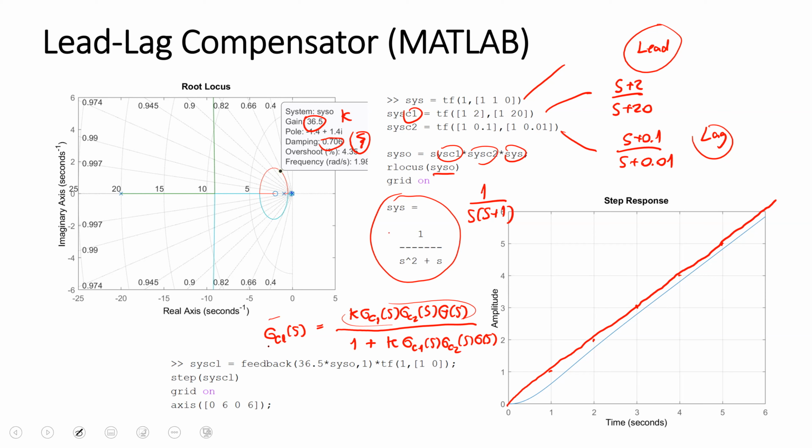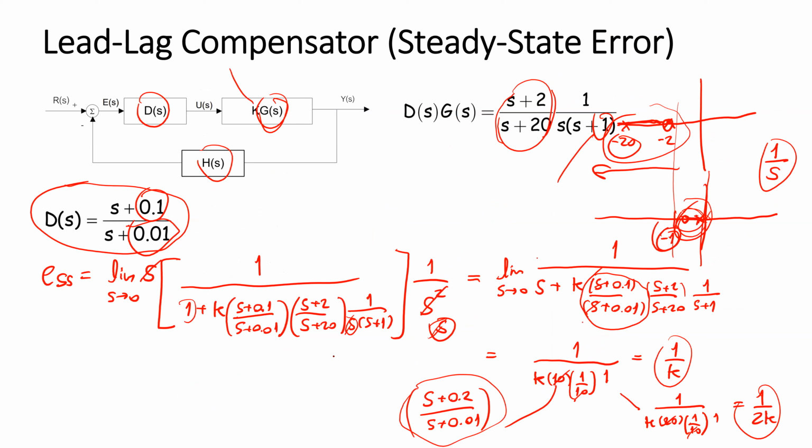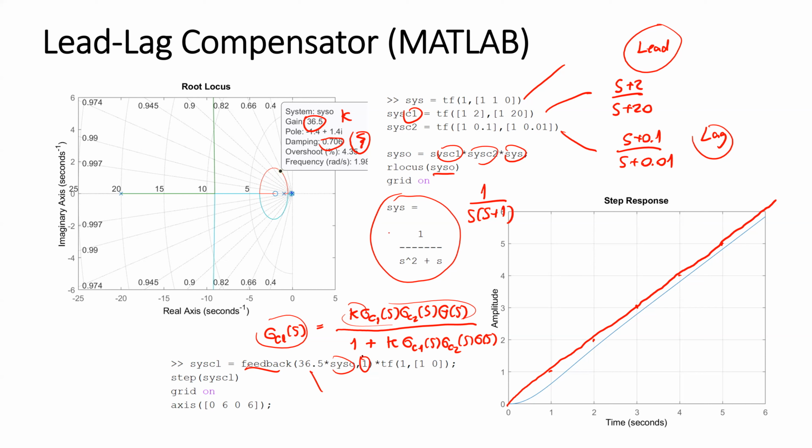So for the closed loop transfer function, you just type the command feedback, the gain, and the open loop. In this case, the feedback is equal to 1. If the sensor has a transfer function, this one is going to be H(S), the transfer function of the sensor, and it will appear in the loop gain, but not in the feed forward gain.